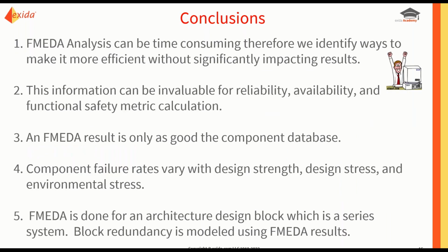So in conclusion, an FMEDA analysis can be time consuming. Therefore, using a commercial tool, we identify ways to make it more efficient without significantly impacting results. The information can be invaluable for reliability, availability, and functional safety metric calculation. The FMEDA result is only as good as the component database, and I can't emphasize this enough.